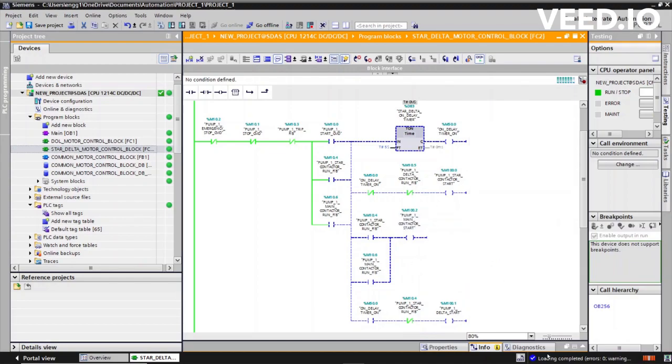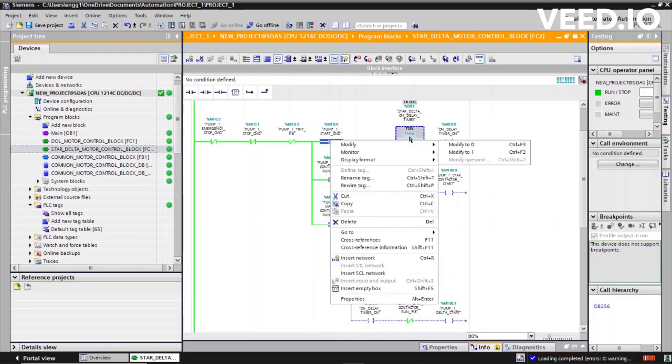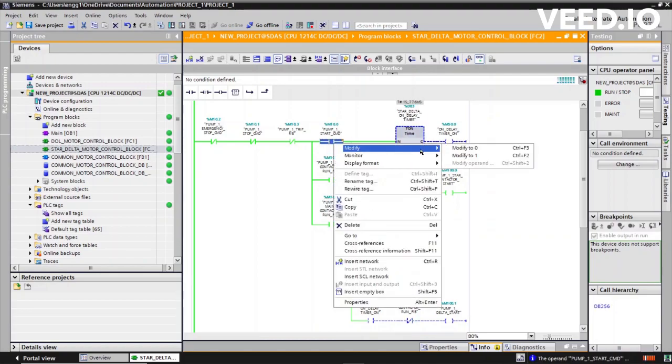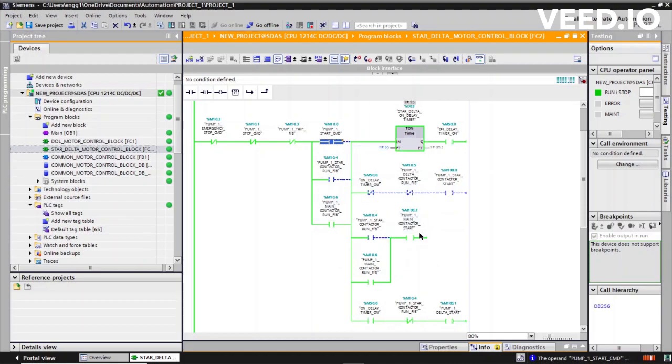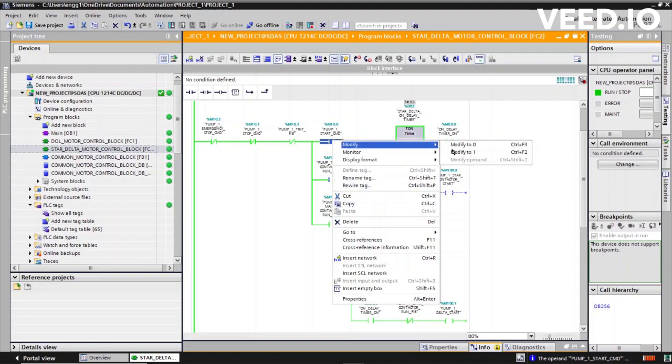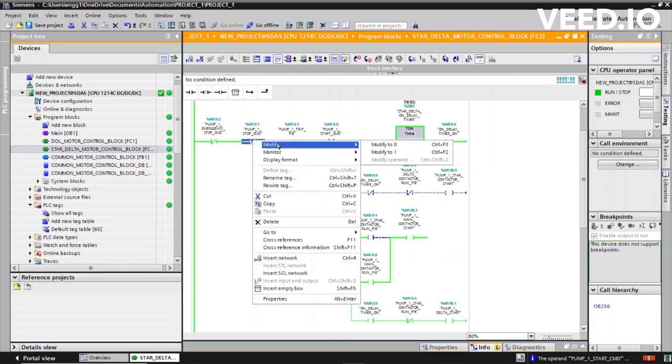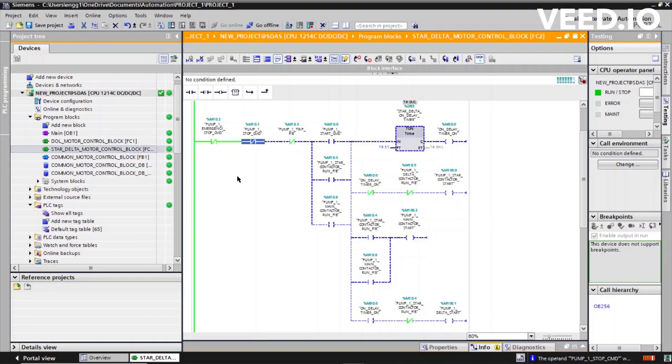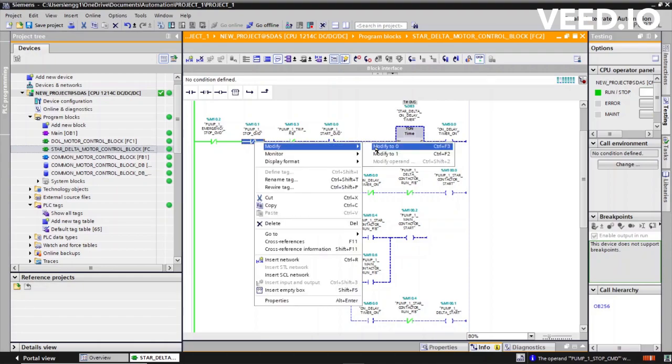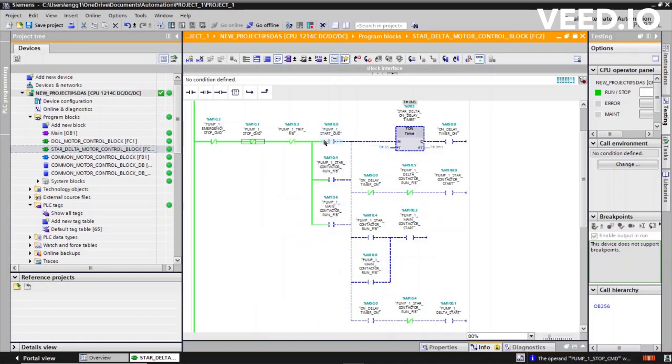But before that I want to share one thing, that I used the contactors' running feedback as interlocks to each other. So during this simulation this feedback cannot activate, so I made a logic in another network to activate this running feedback directly by activating the outputs. This is not part of your lesson, so I didn't show you today. You can try it by yourself, that will be better for your knowledge. If you need any further help, you must comment. Just watch properly, learn and keep practicing.